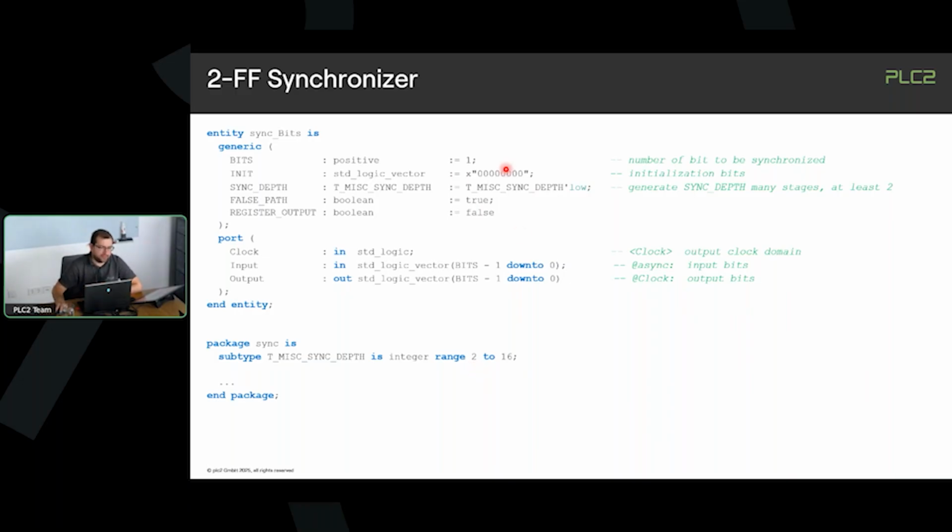In case the user has overwritten in an instantiation, this, let's say with 3, and you set the value here to 4, the synthesis will complain because it's not inside of the range of the subtype, and you can figure out at synthesis time where someone is specifying by hand a value that's too low. So it's also error detecting where you have smaller implementations or shorter implementations.